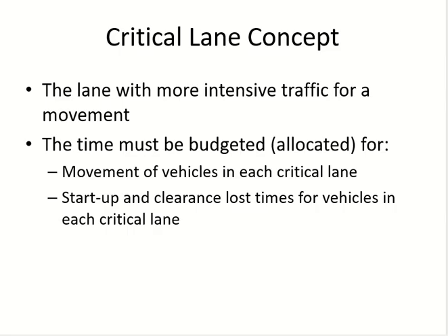And we are using parameters here which may change according to lanes. For example, lost time. For example, headway. The headway is the distance between, or the time interval between 2 vehicles. It can be different for turning. It can be different for heavy vehicles, right? Heavy vehicles do not keep maintaining the same headway. They do not have the same lost time.